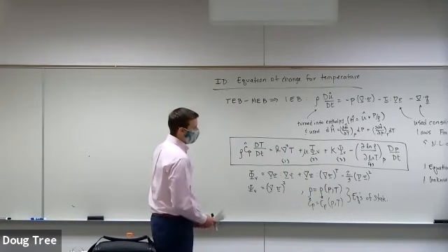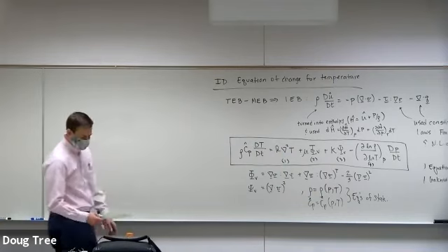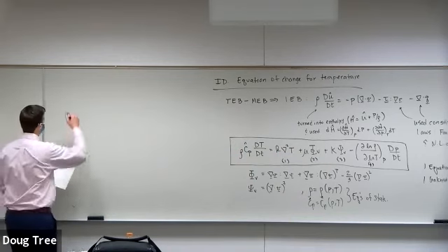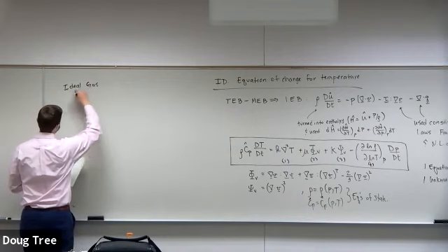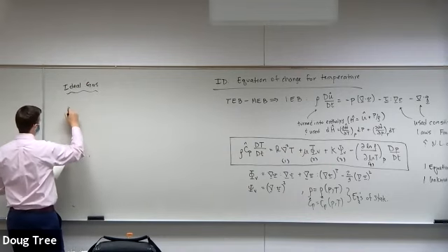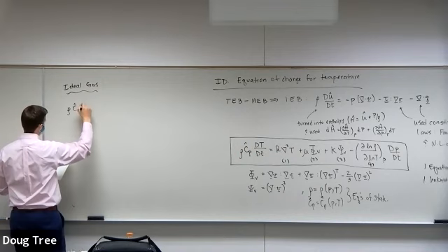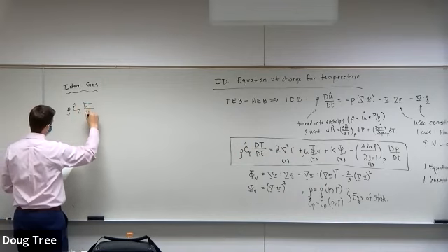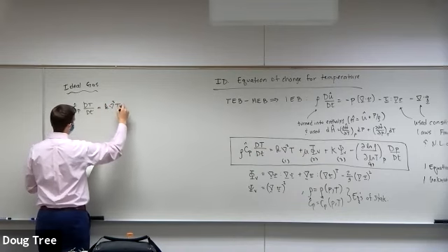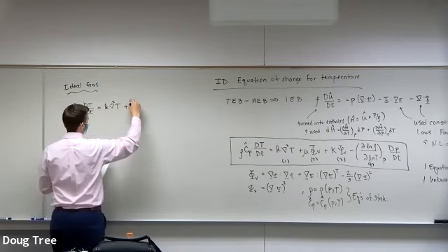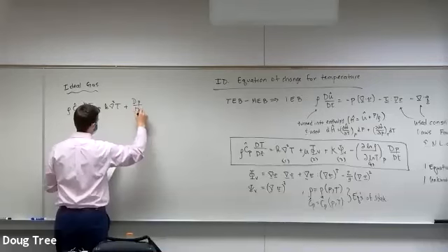So we can also drop those two terms. So for an ideal gas then, what we'll get is rho C sub P dT dt is equal to K del squared T plus dP dt.